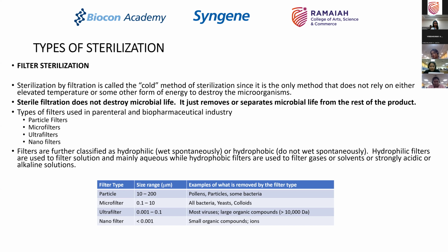So, when you look at the kind of filters you'll be using, if you are using in sterile manufacturing an aqueous based product and you want to filter it, you would generally use a hydrophilic filter. If you were in the same process using air pressure or nitrogen pressure to drive the liquid from one equipment to the other or through the filter, then the air would be filtered through a hydrophobic filter. So you will again see hydrophobic filters and hydrophilic filters in your applications when you go inside the industry.